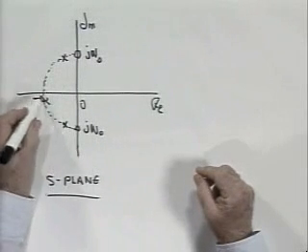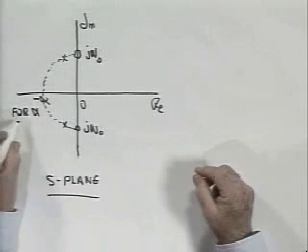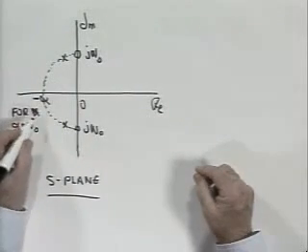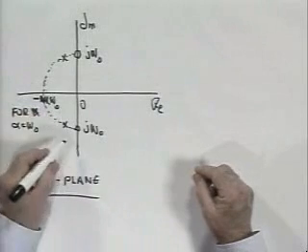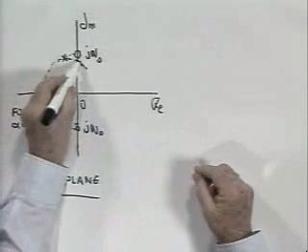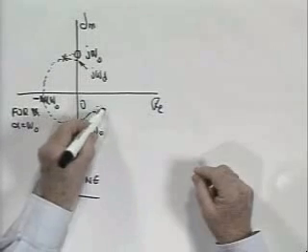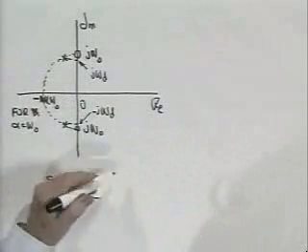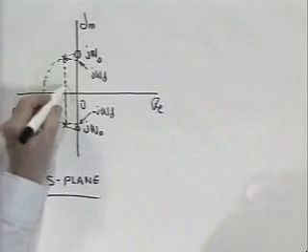I'm sorry, this is minus alpha for alpha equals omega naught. That defines this semicircle. So I really ought to be clear about this and, instead of calling it minus alpha, I ought to call it minus omega naught. And the intersection with the vertical axis is at j omega d and at minus j omega d. So we got a pole zero pair in the positive half plane, a pole zero pair in the negative half imaginary plane. And the zeros are off the axis to the left. The value of the intercept here is just alpha.